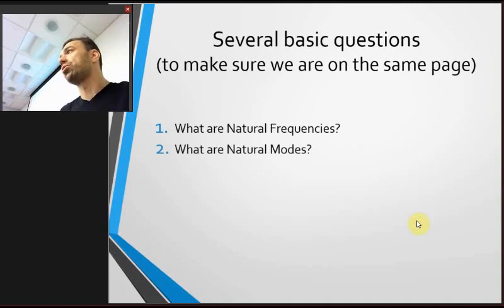What are the natural modes? Natural modes are the vibration shapes that are associated with any natural frequency. So it comes in pairs. Natural frequency comes with natural mode. Okay, I'll have some figure later in the PowerPoint.